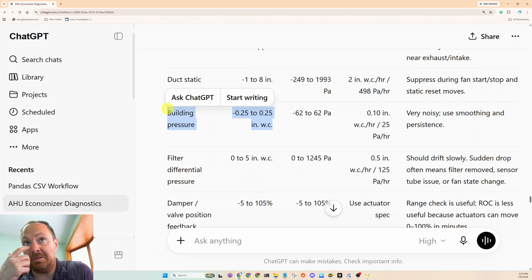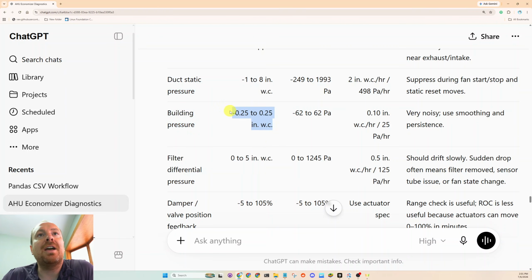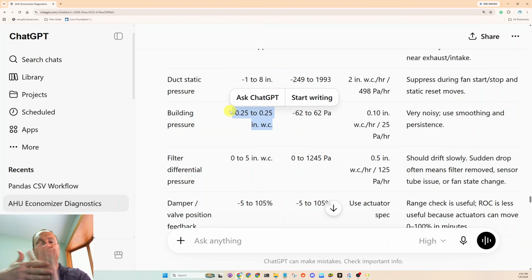I would work with a test and balancing contractor in case the makeup air system failed. For the research exhaust systems, we would have an allowable pressure differential between doors so people could escape. If there's a fire, the exhaust system's still running, the makeup air unit quit. There are definitely some allowable ranges there, and these sensors need to be in calibration.